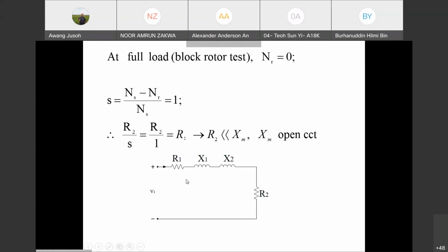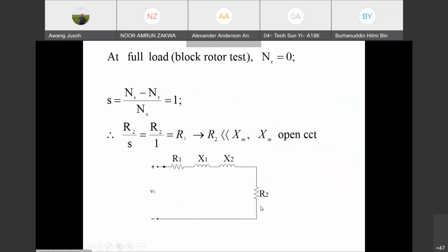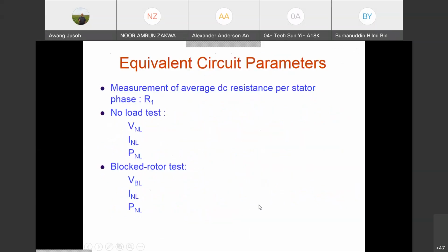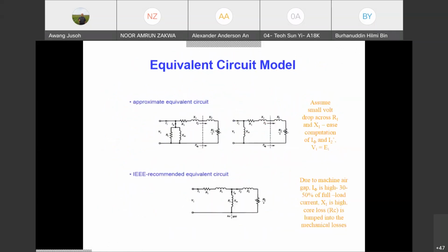Okay. Then you know Z already. So the square root of Z squared minus R block rotor squared gives you X, the reactance, which is X1 plus X2. And then you can find X1 and X2, just like that. After that, you get the complete circuit. You get the component for XM, X1, and here the components for this one. Then you can construct the circuit, which equals this one. You get the complete circuit for your induction motor now.